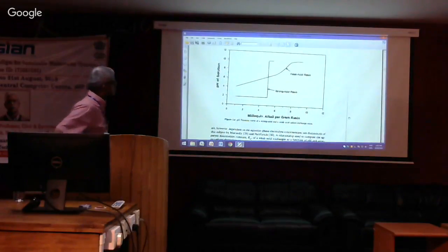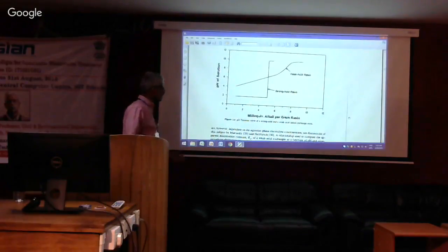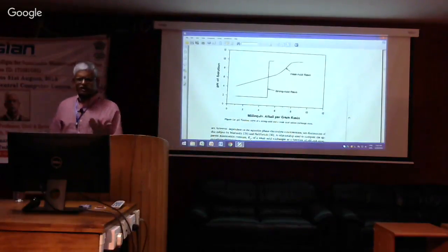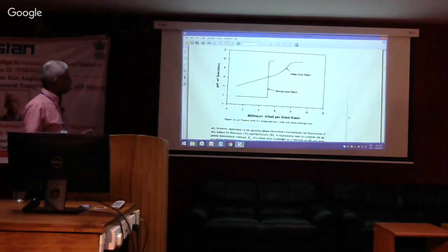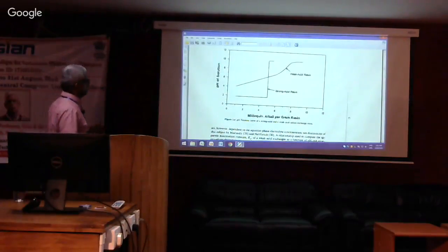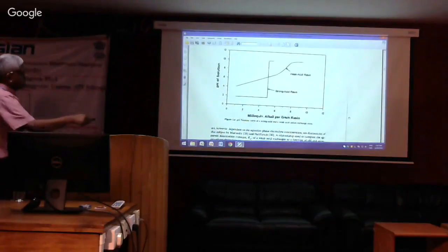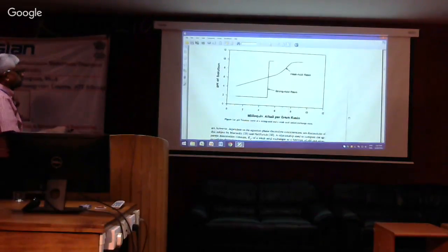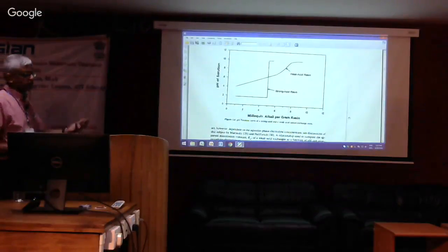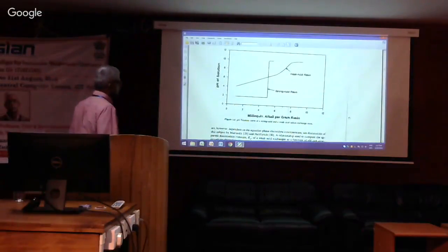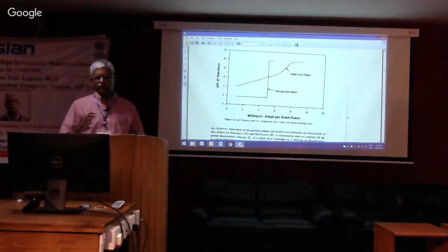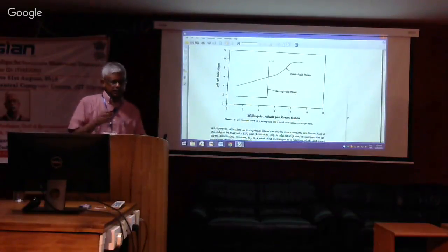So if you look at a strong acid resin, then strong acid resin doesn't really care about the pH. So when you titrate, then you get this very classic curve. Whereas in the weak acid, as you know, because it has this affinity for hydrogen, the pH plays an important role. So that's why when we deal with a strong acid resin, we have no problem, it will work in any pH.